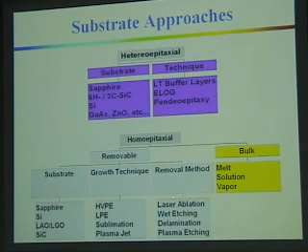And one way to remove the substrate, for example, is to ablate the substrate away. Of course, you destroy your substrate. If it's expensive and it's not reusable, it's removable but not reusable. Another way is to etch it. Again, that's a destructive removal technique. Another way is delamination, which is non-destructive. That is, we can get it to separate.